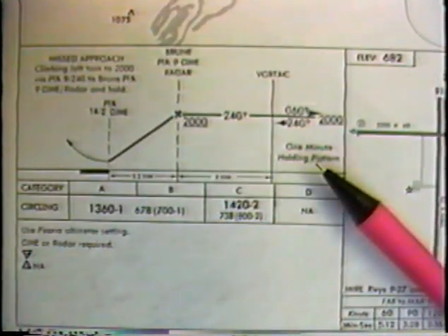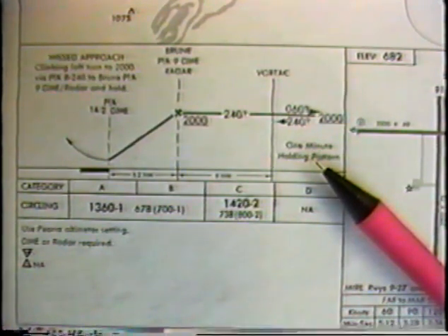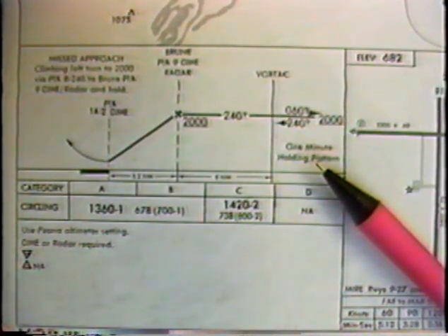The length of the holding pattern leg is usually 1 minute and is shown on the profile view. If you need more time to get established inbound at the proper altitude, advise ATC that you wish to make another circuit in the hold. Do not extend the length of the holding pattern legs.